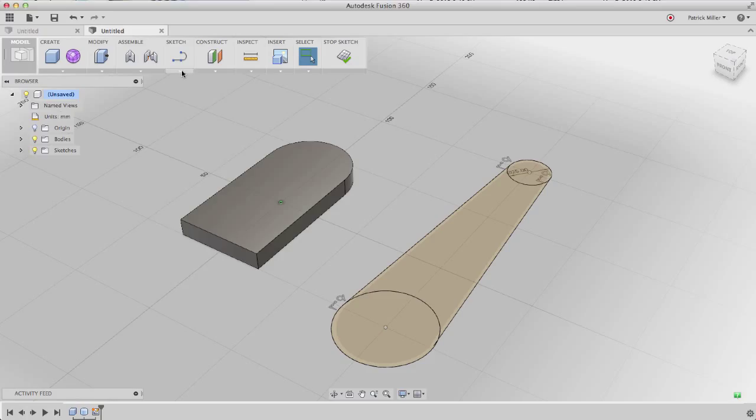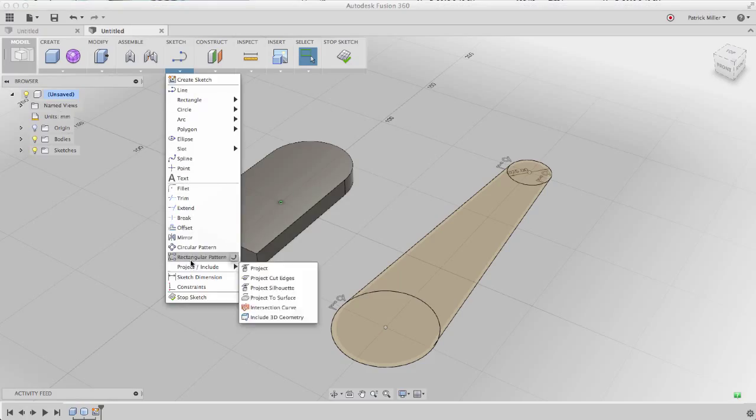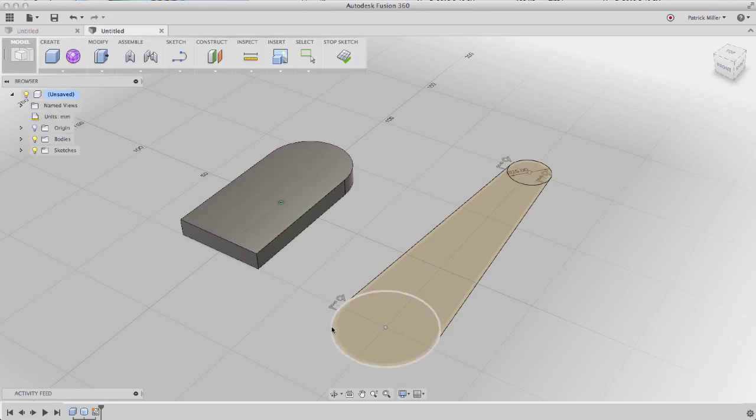Now I'm going to go in and add some dimensions to lock down the size of this geometry. So I'll pick on the first circle, that's 50 millimeters. This one, because I typed a value, automatically got a dimension. And then if I pick the 2 circles, I get a linear dimension between the center points. I do this so that it locks down the geometry, but also lets me make changes. So I can change that from 150 to 120. And it looks like I missed a pick when I defined that line, so I can just drag that back to my circle. So that's my 2D sketch profile.